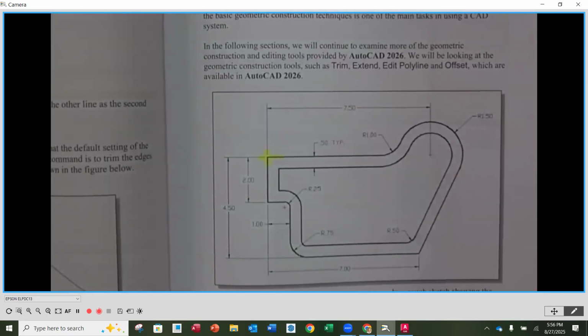Now, a gasket is used to sandwich between two parts in order to hold in whatever is on the inside or keep out whatever's on the outside. Sometimes it might be to keep dirt out. Sometimes it might be to keep liquids in, okay? They can be made out of rubber, cork, different types of material, okay? This gasket is usually going to take the profile of whatever it's sandwiched between. We don't really know the application here, but this is what our gasket is going to look like.